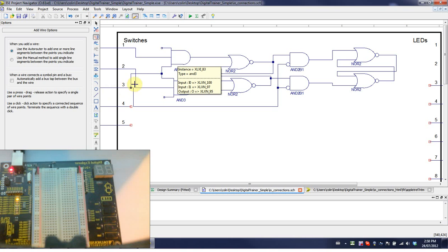So you notice the clock, when it's high, will enable these two, and the data will go through to this latch. But you notice the clock, the enable pin for the second part here, has that circle, meaning it's complemented. So what this means is that the enable pin is active low. When it's high, the data loads through the first part, and then when the clock goes low, it loads through to the second part. So this is how we create a flip-flop from a latch, because it's only when the clock changes that the data goes through to the output.